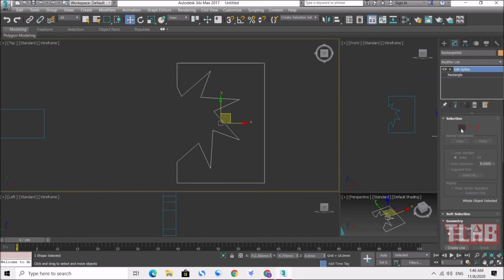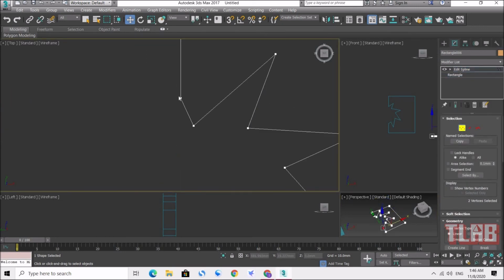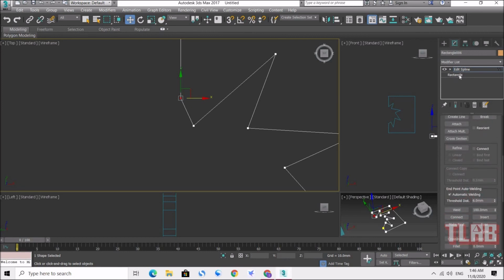Okay, now go back to select Vertex. Okay, double check. This point inside has another point. Actually there are 2 points. So select them together and then move down. Okay, find this one, where? Okay, there is only one. But for us, because this is a Weld threshold, that means the number you can put bigger, maybe 100. I think that's enough for this.